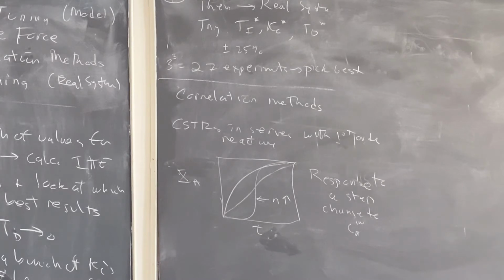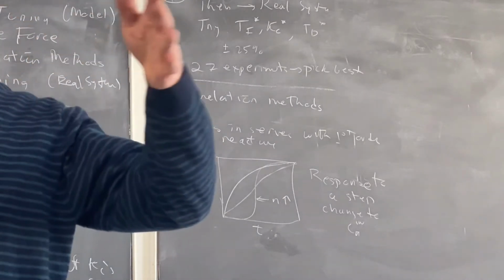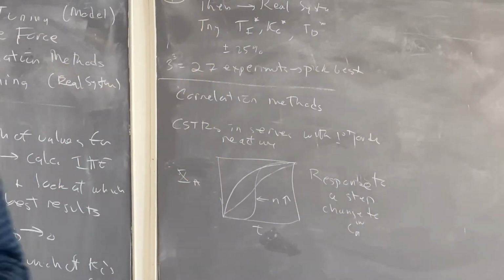But it's obviously much more muted. This was a step change. This is a change in the derivative. This is going to take a little longer to see. This is going to take a little longer. So the point here is that when I have a nonlinear process, there's more of a delay before the output feels the change in the input.